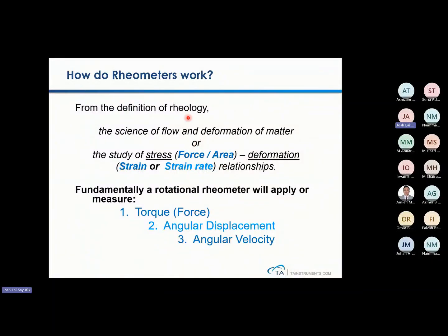So rheological testing is typically to study the sample's flow behavior and deformation of matter. Flow behavior typically relates to viscosity measurements, while deformation of matter typically relates to viscoelastic properties. Later in this presentation, I will share more details about these two common tests. But before that, we need to understand how the shear stress, shear rate, or strain rate is measured